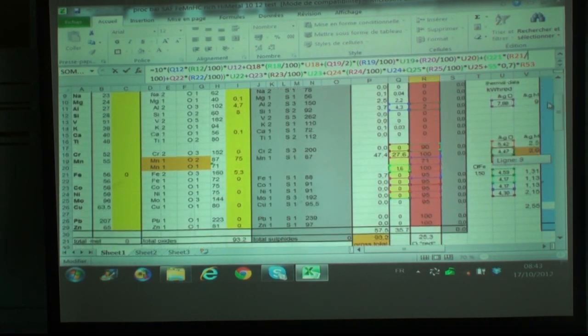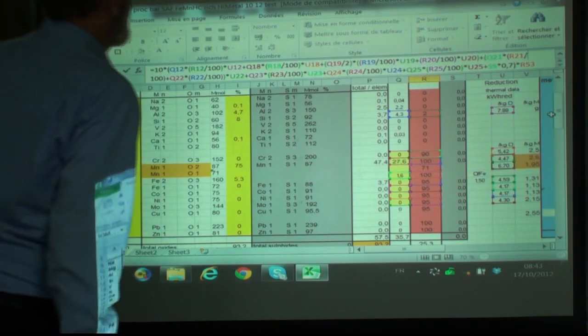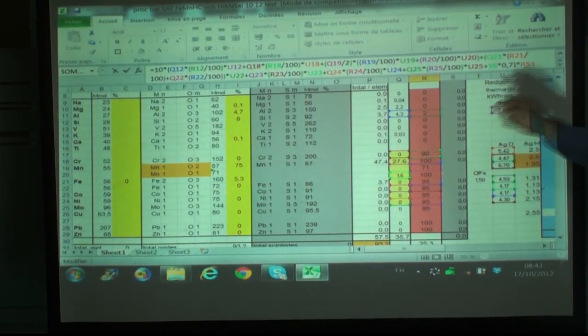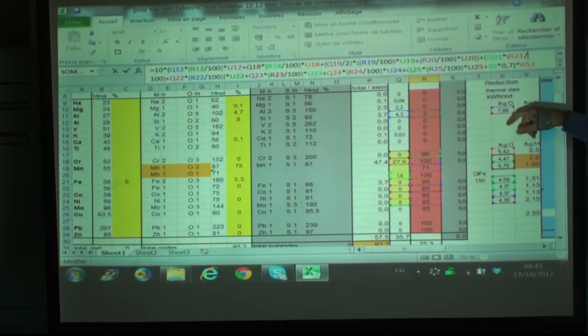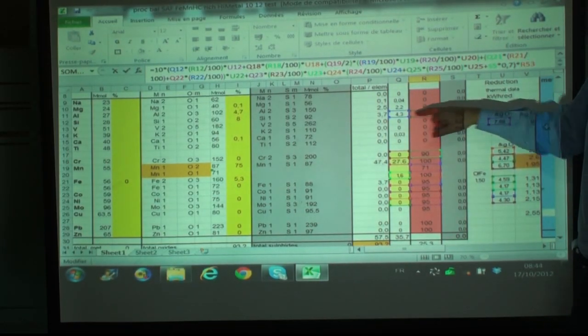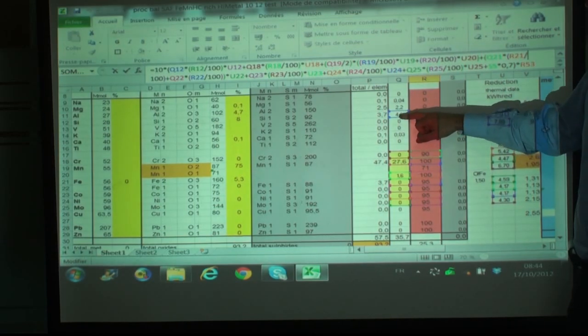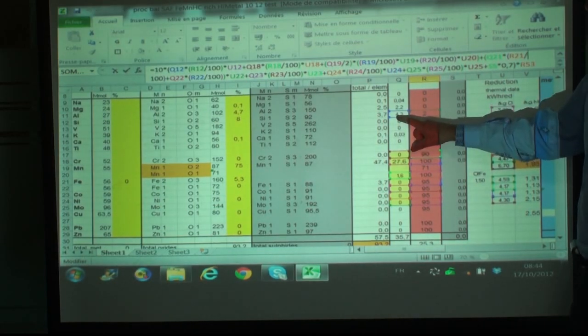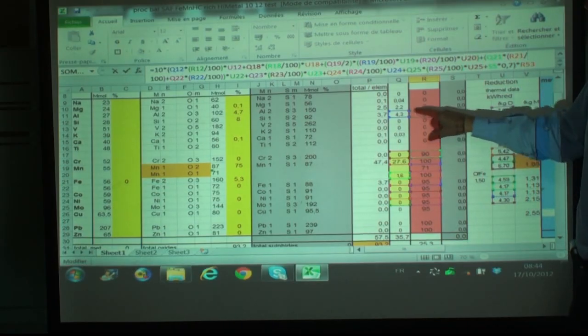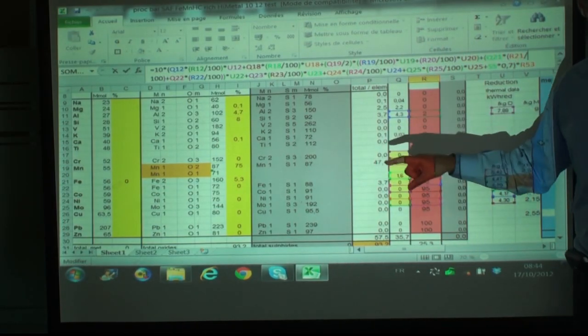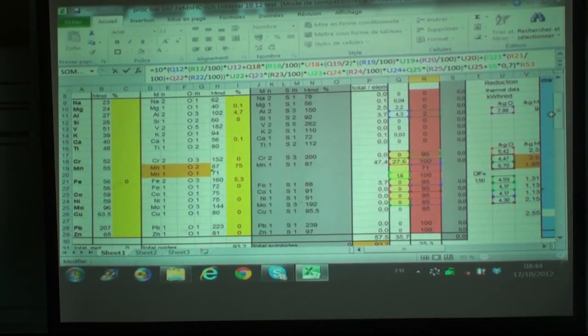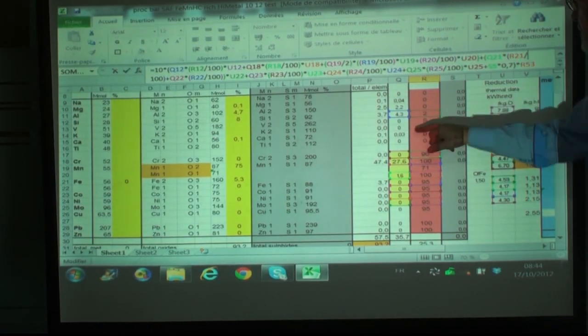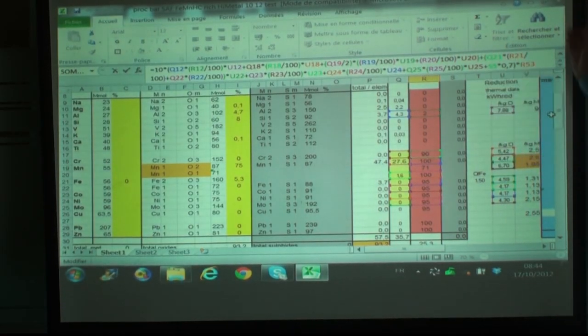And what is done is simply that here you have the amount of oxygen which is really removed. Here you have the oxygen and you multiply by the yield of reduction to have the real oxygen removed, and then you multiply by the reaction heat per kilo oxygen. And this you do for each line which is used.